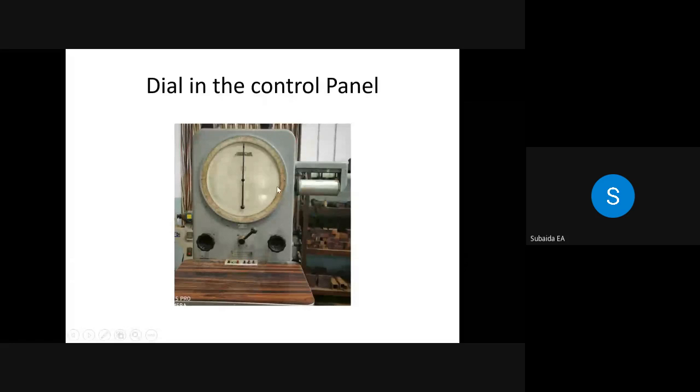Then we can note down the maximum value using the dummy needle, then the breaking value, where the actual black needle will stop, that is the breaking point. These values we can note down. Then we can note down the elongation. This extensometer will not be kept for the entire duration, because the specimen is going to break. Before that we will remove it.